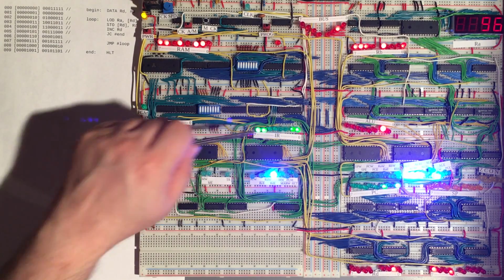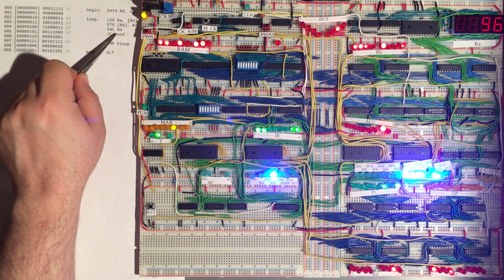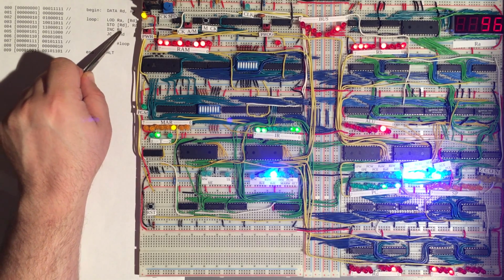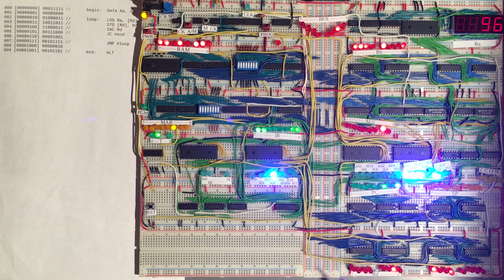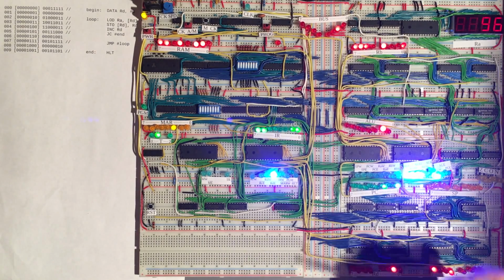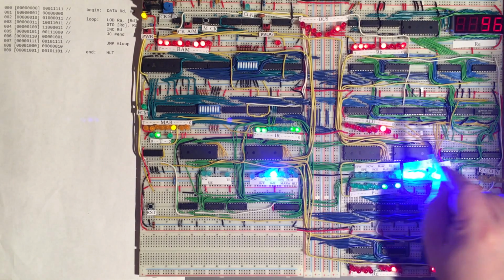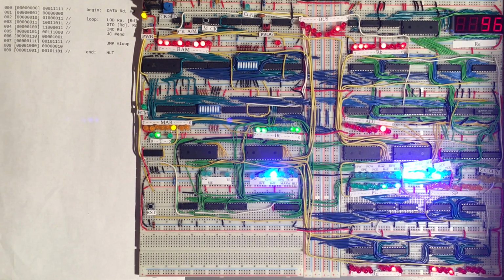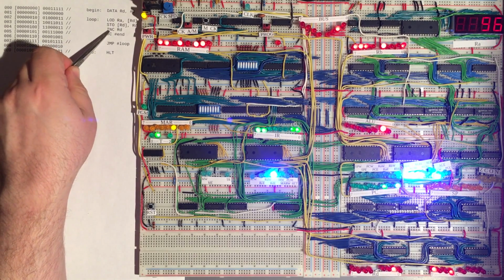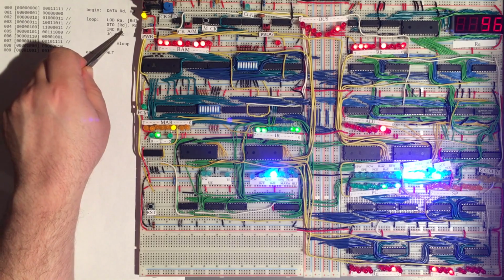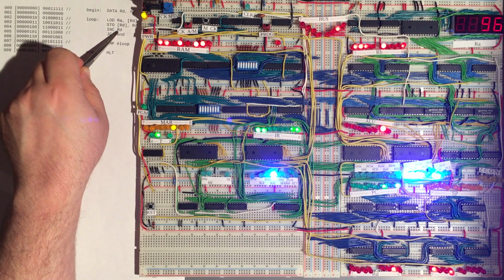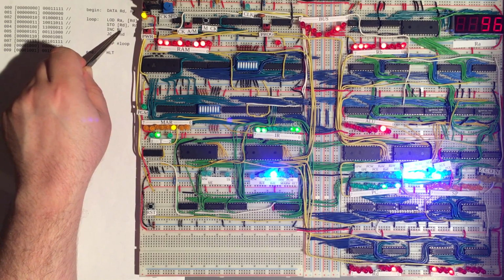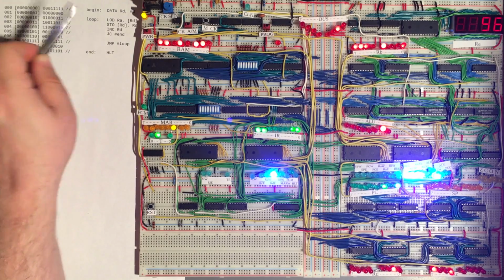And now this is an increase instruction. And so what we want to do for an increase instruction is, we saw that in the episode on the ALU. In fact, what we want to do is to get the contents of that register, which is the D register. So we're enabling the D register onto the bus. So there it is. And by enabling it onto the bus, that will automatically become the A input into our ALU. And for an increase, we want to set the B input to be 0 and then add, actively assert a carry in to our ALU. And by doing that, we will achieve the calculation of the value of the A input of the ALU plus 1, and the B input will be set to 0.